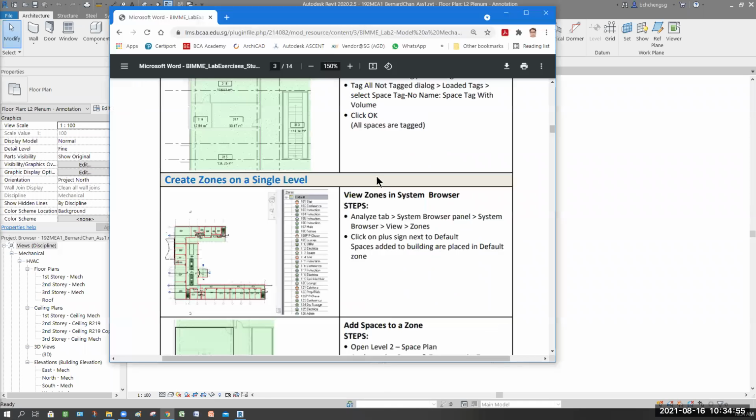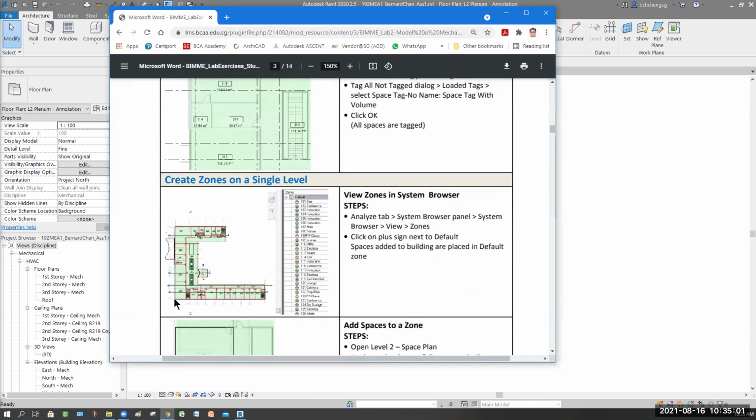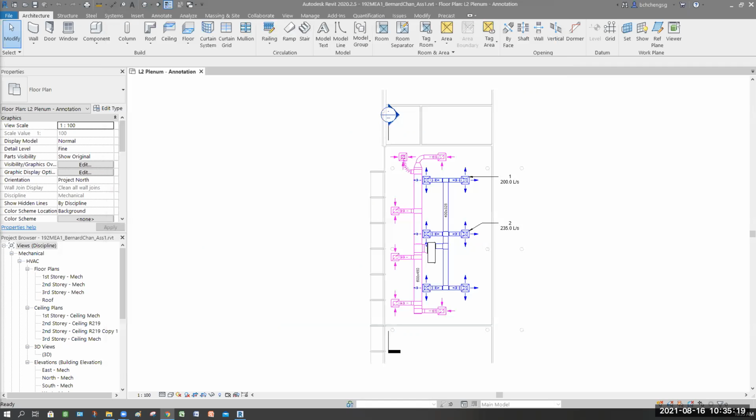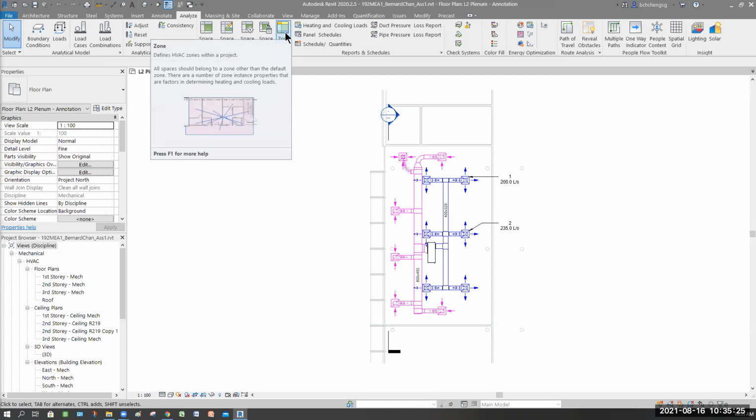You see this? It is creating a zone, so it's just how things are going to be connected. Zone so far is mainly for what? Central aircon, right? So when you press this button, this particular zone will have air supply coming in. So zoning, where can I get the command zone? Analyze, right? So zone is here. So actually quite straightforward. You can define a zone and just click the component, and they automatically link. But first thing first, you need to have space.